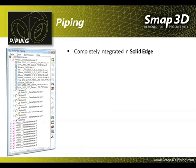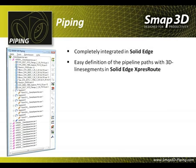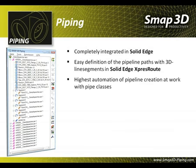One important point is that the software is fully integrated into Solid Edge. Further, the easy definition of the pipeline paths with 3D line segments of Solid Edge Xpress Route is a benefit for the user. Because Smap 3D Piping works with pipe classes, we can reach the highest step of automation for the 3D pipeline creation. This allows the user the fully automatic generation of complete piping systems.